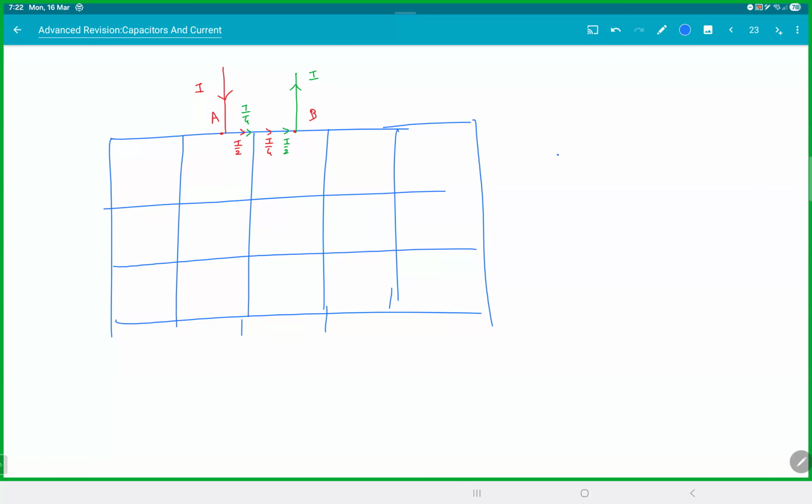And now if you write the resistance between A and B, we have a half resistor here, R by 2, because that is half the branch. Another half resistance, R by 2, and then comes B. And if you look at the current in both of them, the current here will be I by 2 plus I by 4, 3I by 4, and 3I by 4.